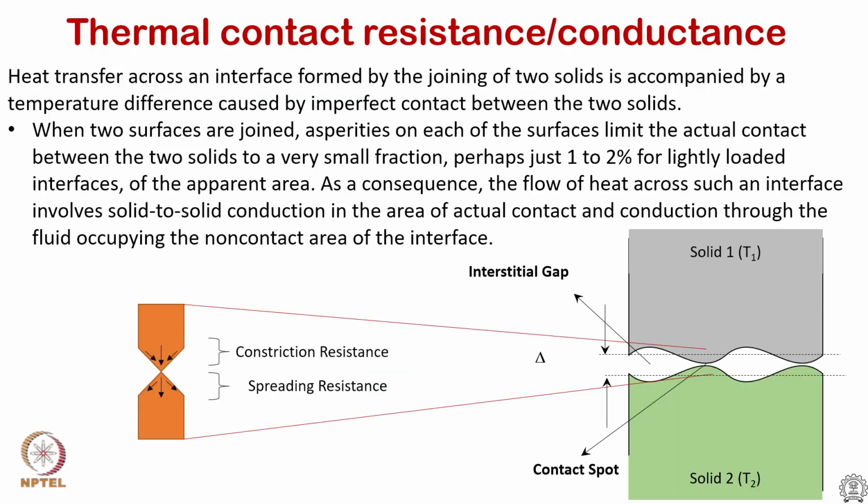So, the last part of this introduction piece is the contact resistance. Any time we bring two materials together in contact, only 1 to 2% are in contact. If I put my two arms together, palms together, I see that very little contact is expected if I put very light load, and this is true for any heat flow device.